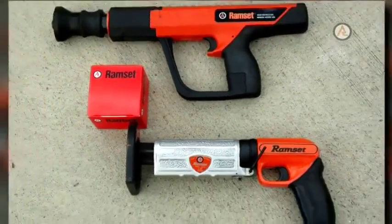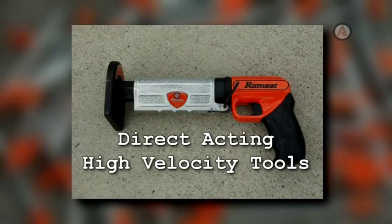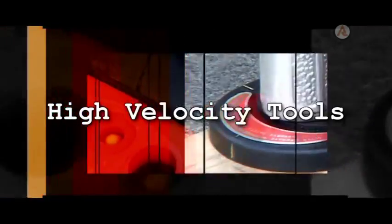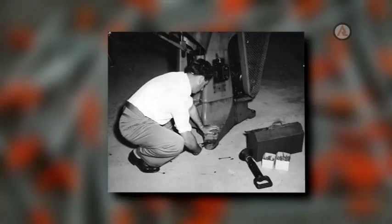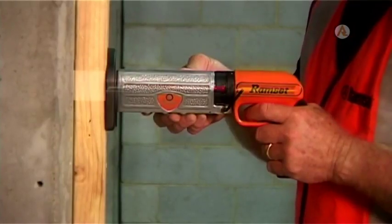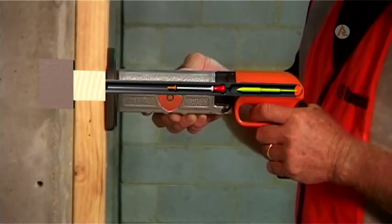There are two distinct types of powder-actuated fastening tools used around the world. These are direct-acting high-velocity tools and indirect-acting low-velocity tools. High-velocity powder-actuated tools were first introduced in Australia in the 1950s by Ramset. High-velocity tools are designed so that the energy contained within the power load is transferred directly to the fastener.